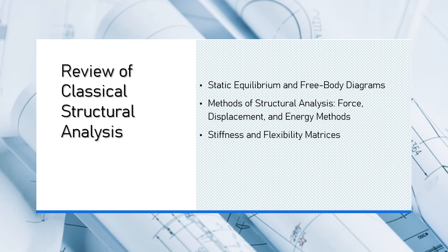5. Assume directions for unknown forces. If there are unknown forces or reactions, assume their directions, upward, downward, etc. If the assumed direction turns out to be incorrect, i.e., the value of the force is negative, you will know that the actual force direction is opposite to the assumption.